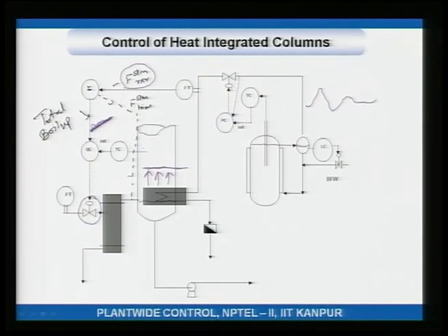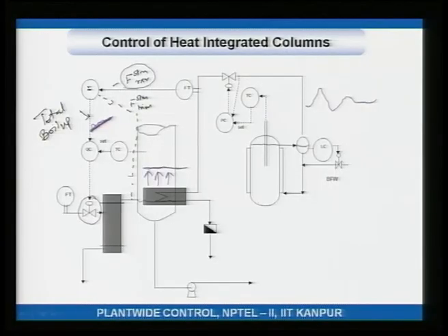All right. So, in this control scheme, fluctuations in the steam generated from the reaction section do not cause fluctuations in the tray temperature. I would not say do not cause, it causes very little fluctuation in the tray temperature. Okay. So, this is a better scheme than what we were doing here.